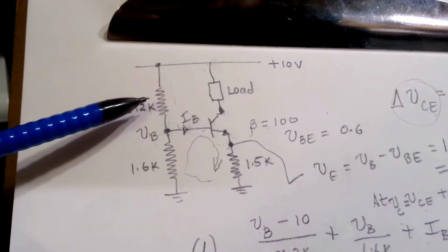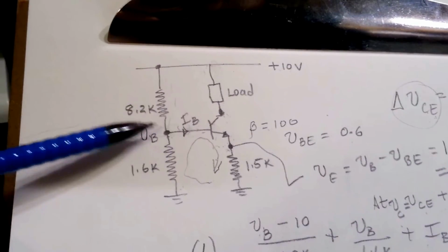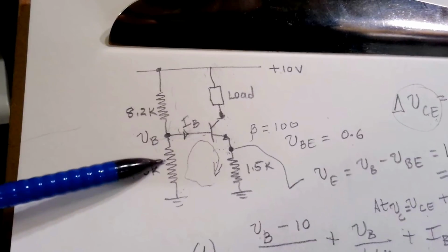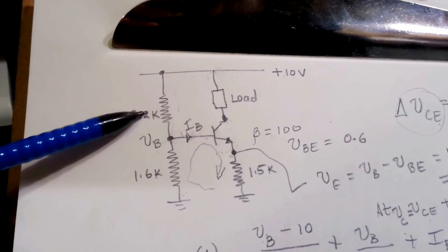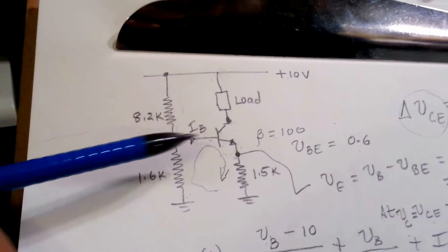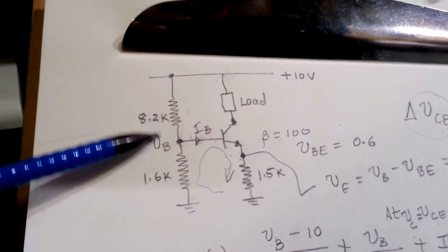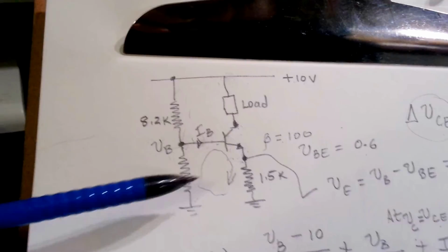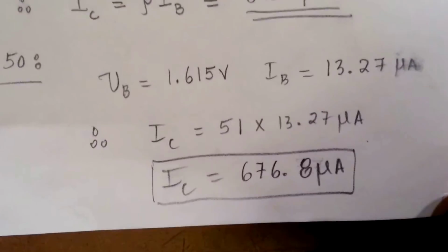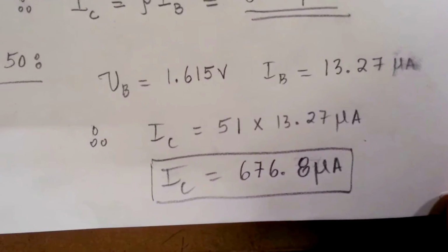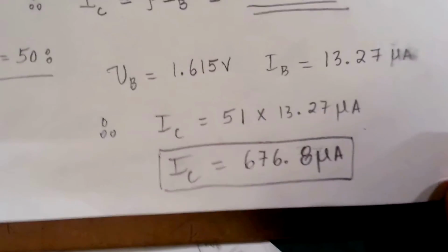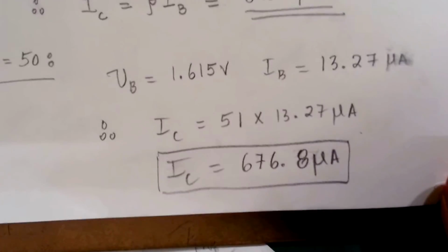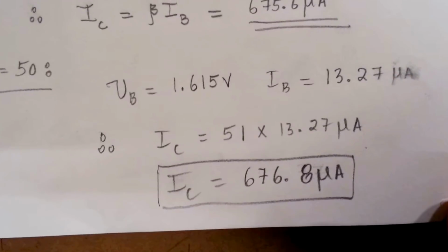And if you parallel these two to get the base resistance here, compared to 150k, the parallel combination is very small. So really, this biasing section doesn't load the base. This is a very good way to bias, and as you can see, recalculating for a different beta proves that it's a good biasing. So that's part B, and this is within the compliance range, as you can see.